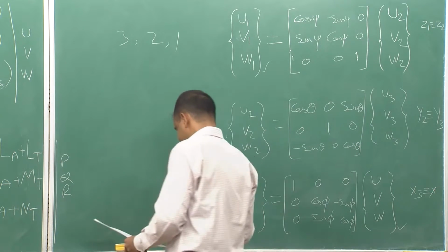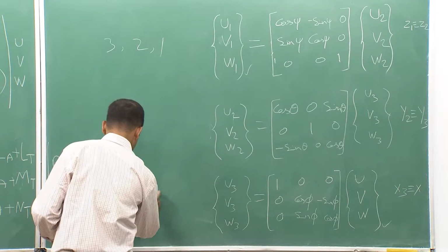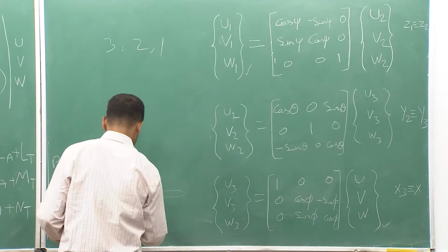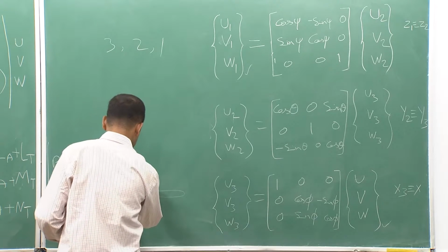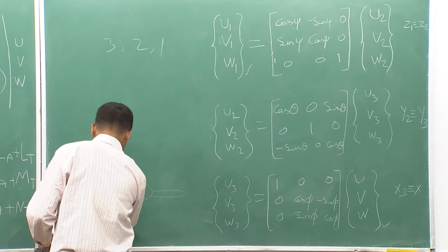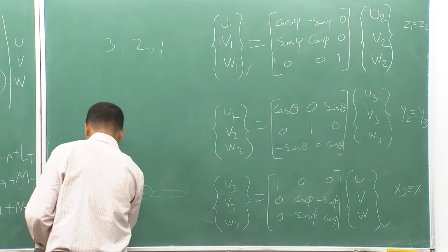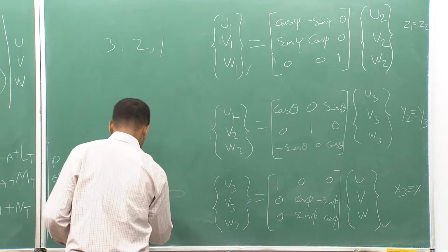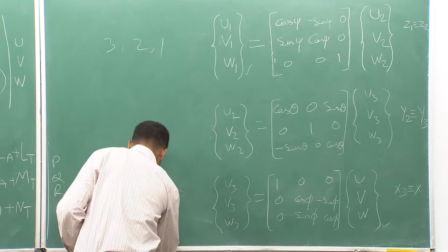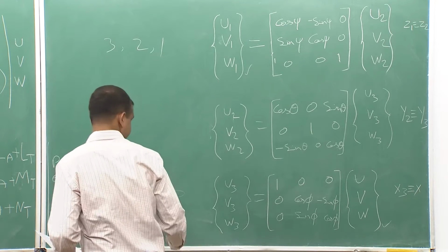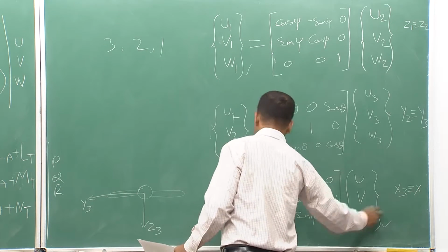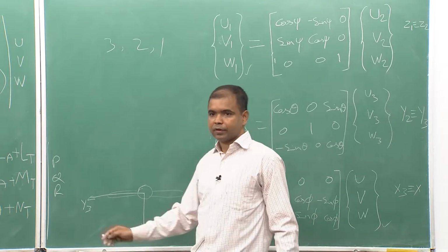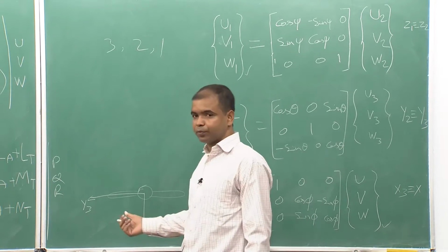In third rotation we have front view of the aircraft. If this is my front view, then suppose this is our y3 and this is z3. For this rotation, for the positive phi, the right wing down is the positive phi.